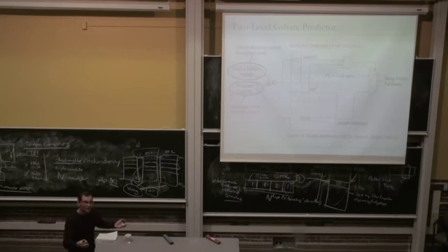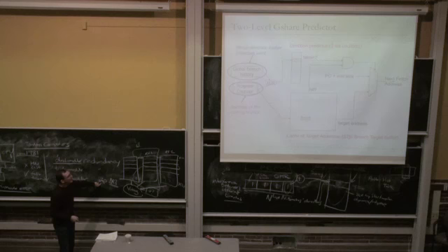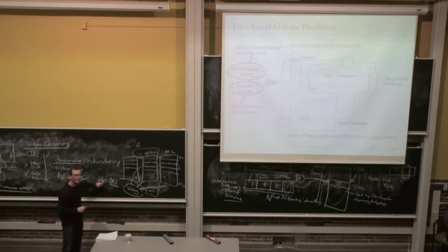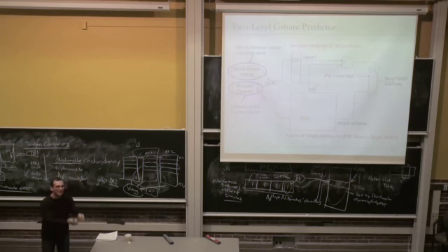Last time I saw this indirect branch, and it had this global branch history coming into it, the target was this. So this time I'm going to predict the target will be the same as that time. Does that make sense?